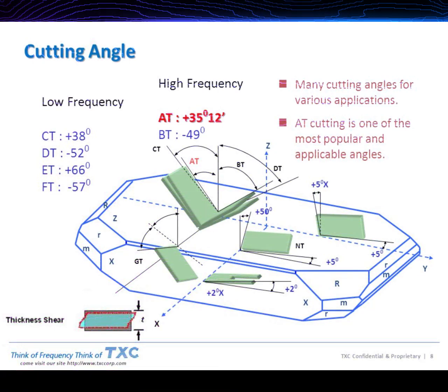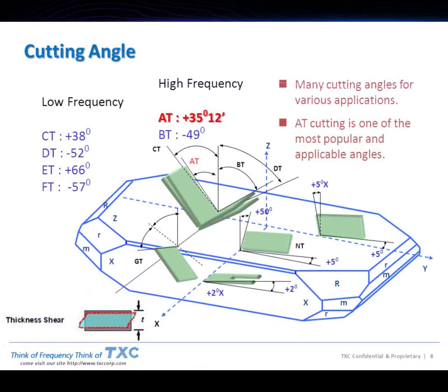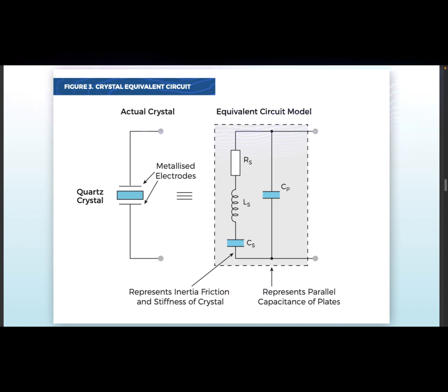Role of the clock. Most electronic systems today are based around a microcontroller, an application-specific integrated circuit, or ASIC, or a system-on-chip, SoC. This contains one or more embedded processors with on-chip memory, peripherals, and external interfaces. The speed at which a processor executes instructions, the movement of data to and from memory, the operation of peripherals, and the data rates of external interfaces are all driven by appropriate clock signals.